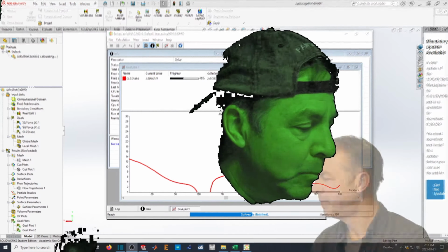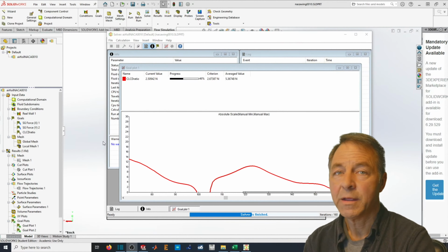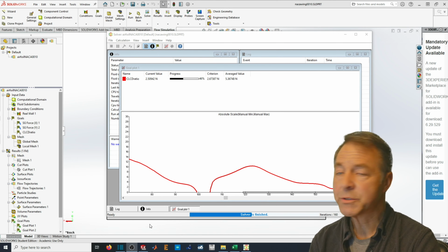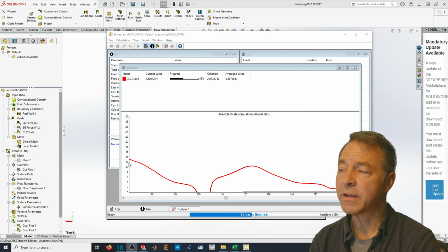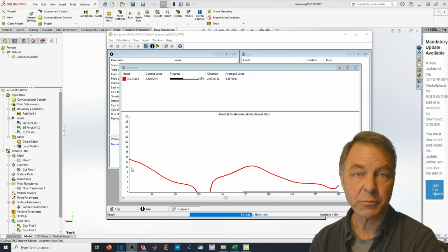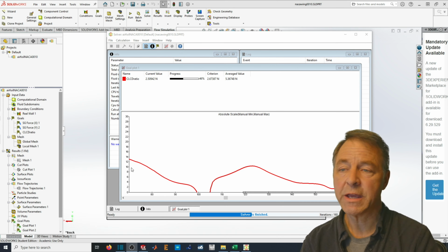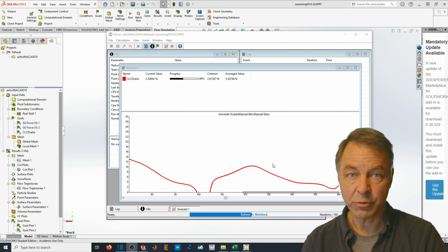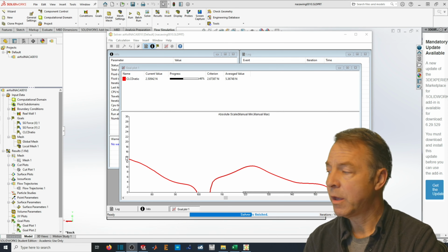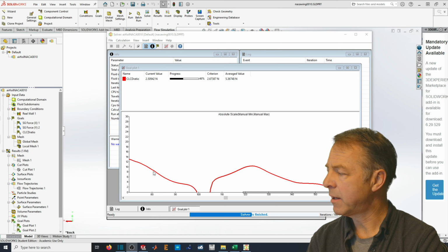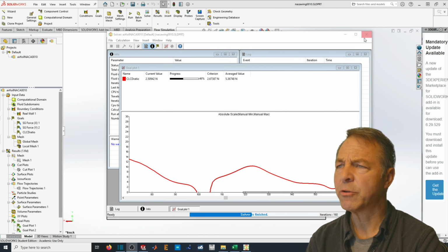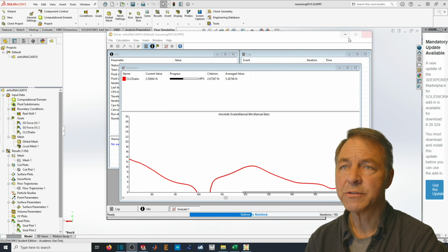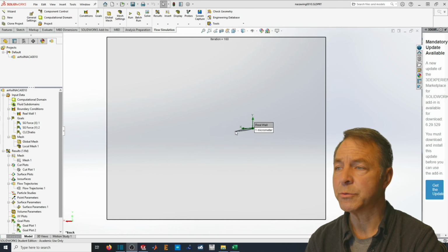There, I've just stopped that calculation. It keeps on going. And notice what's happened. Now, instead of having a nice, steady, consistent result that somewhat agrees with the expectation, all I did was add roughness and a real boundary layer condition. And what I ended up getting was this jumping around, oscillating result. And it didn't look like it was going to be ending very soon.